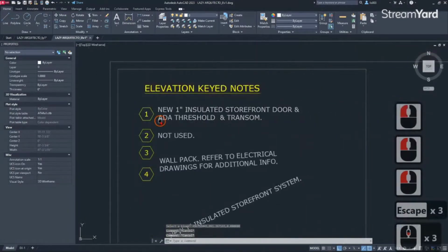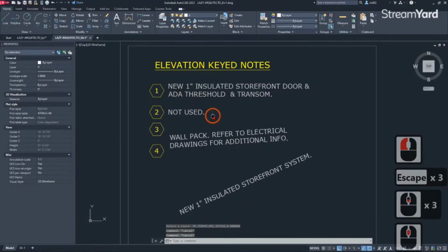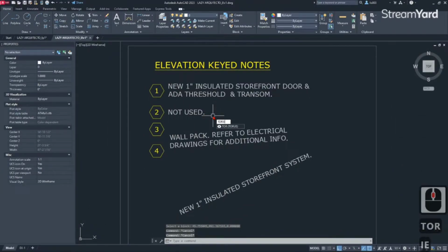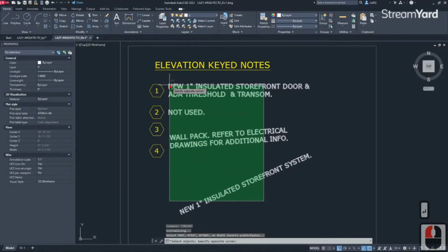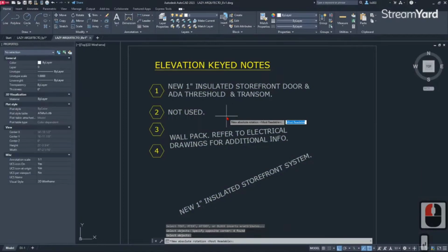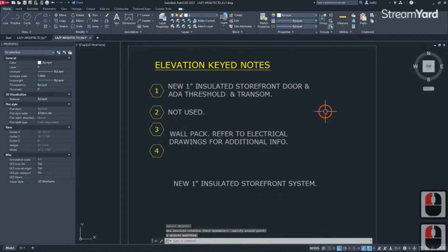All right. So a quick way to rotate or align your objects is using the T-orient command. So again, T-orient, and we can simply press enter. And at this point, we can select all of our text like so, and then press enter again. So here you can use the most readable option, or you can simply click once, click twice, and all of your text would be aligned like so.